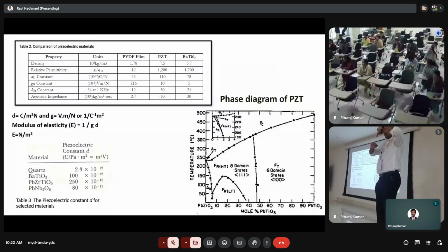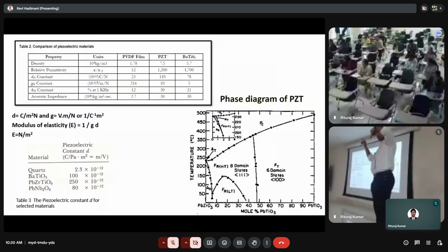Whenever it oscillates, it knows the oscillating frequency. But if the oscillation changes because of the bumps, that small change in the current of the photodiode can measure how big the bump is. That's how you correlate.